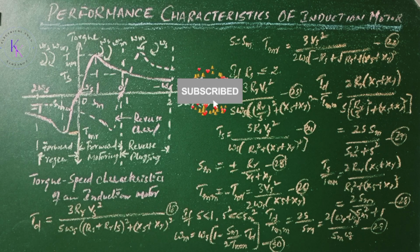percentage. The motor operates essentially at a constant speed. When the load torque exceeds the breakdown torque, the motor stops and the overload protection must immediately disconnect the source to prevent damage due to overheating. It should be noted that for S greater than Sm, the torque decreases despite an increase in the rotor current, and the operation is unstable for most motors.